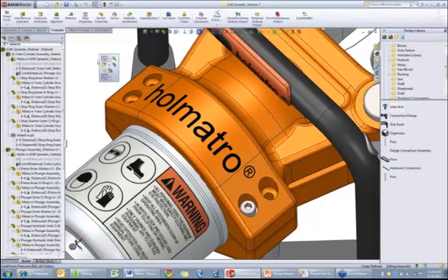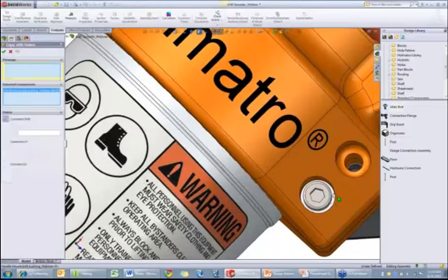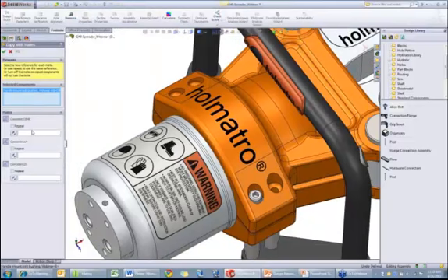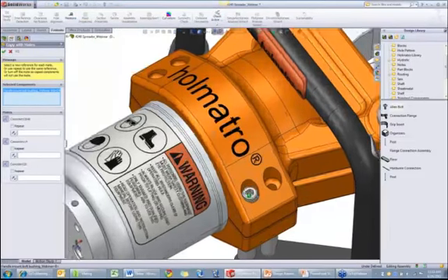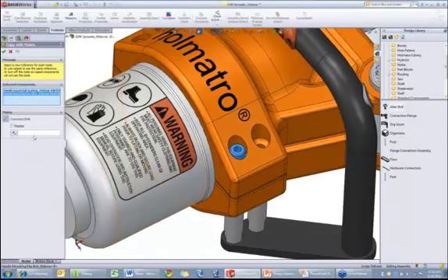And you can find that if you click on your S key and expand the insert components, you'll find copy with mates right there. Or you could also put this button anywhere you want. And see, if I pick on the bushing, you'll notice that there's 3 mates connected to that bushing. If I pick on the bushing and the screw, then I'm down to just 1 mate that I have to copy, because it's automatically going to copy the mates between those 2 components.